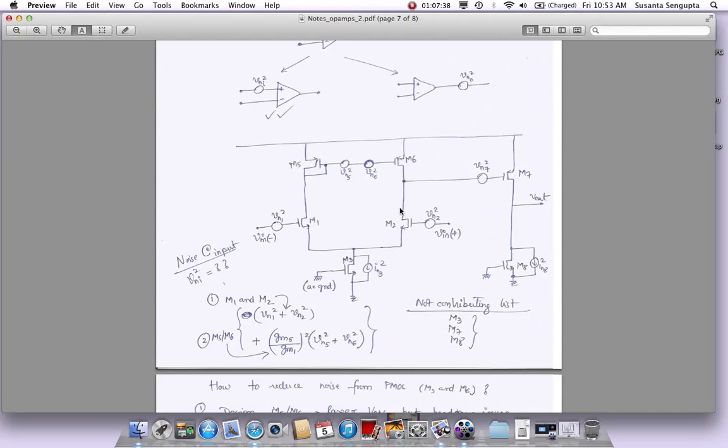When I'm doing it, you might be getting confused. How come you have noise voltage here and here? You got two currents here. No, when we do this kind of analysis, we only pick one at a time, assuming everything else is 0. So this is 0, there is no input here. Only one of them is there.